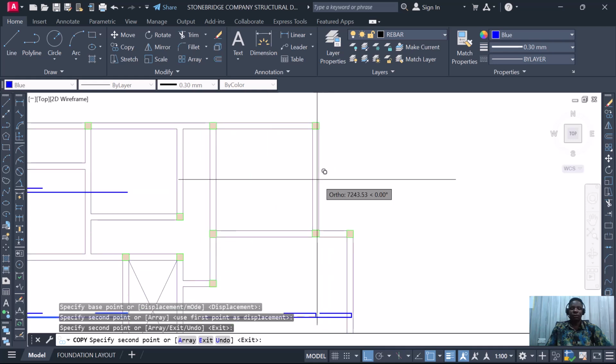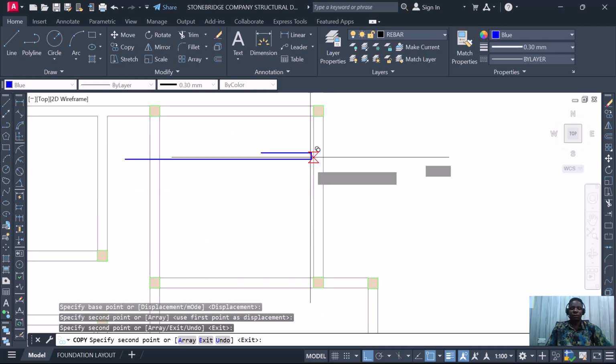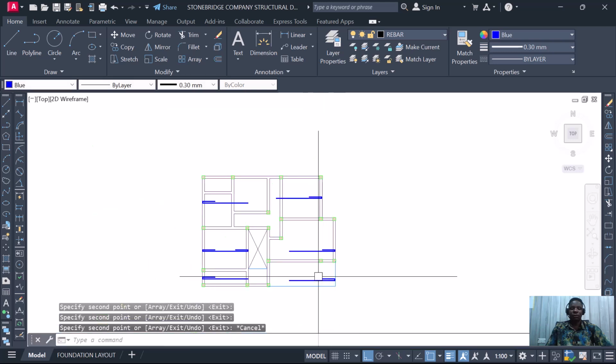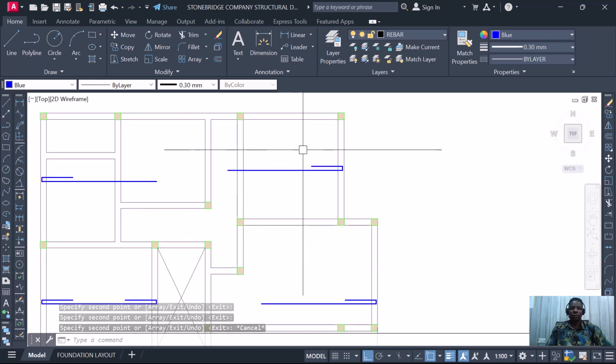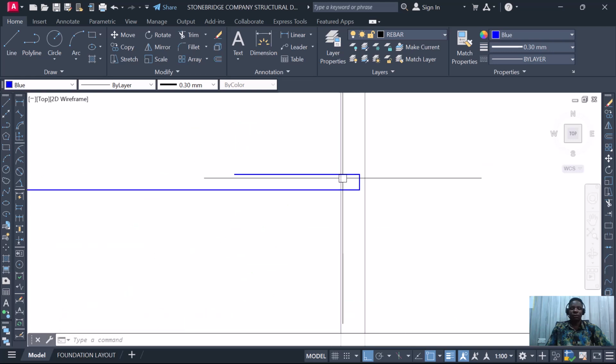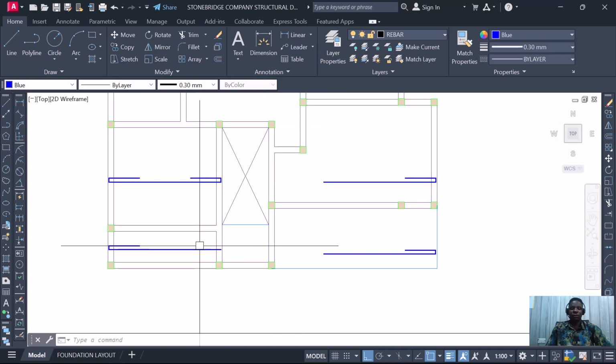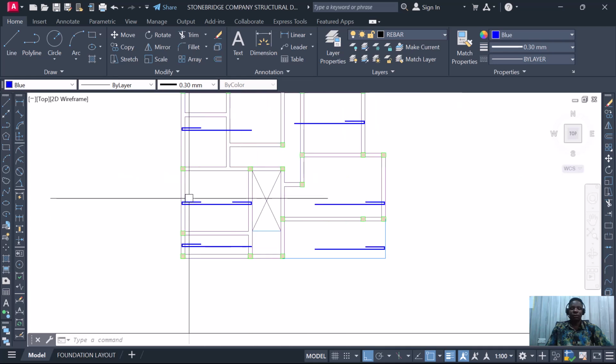Now about this section, we're going to take this over here. Since we have done with our calculator, we can now close the calculator, so we'll have a very successful view. All right, so here we'll do the same thing, and over here you can see we'll have a different shape. Mind you, we are putting all of this inside the beam, not at the face of this beam. This anchor needs to anchor inside the beam and have a return. The same thing to this other side.